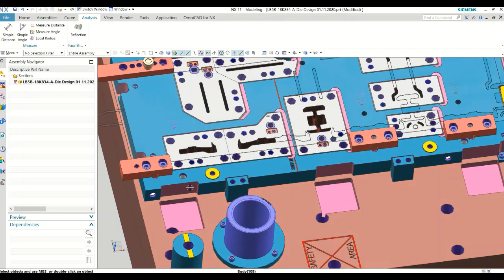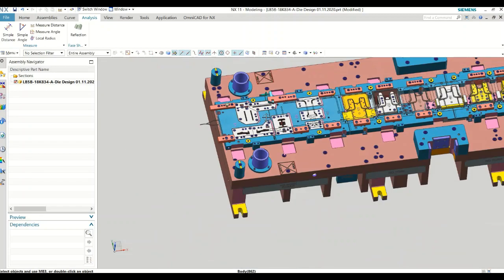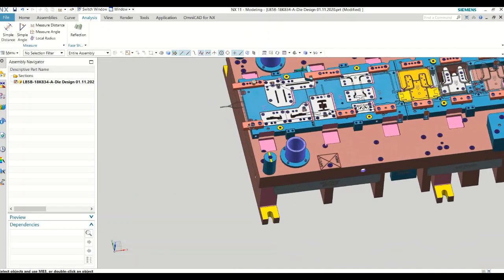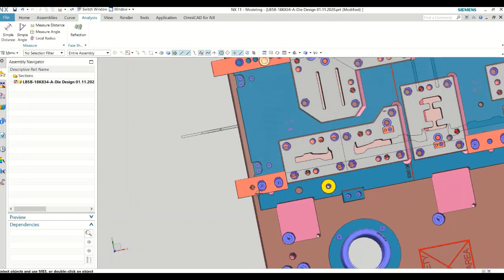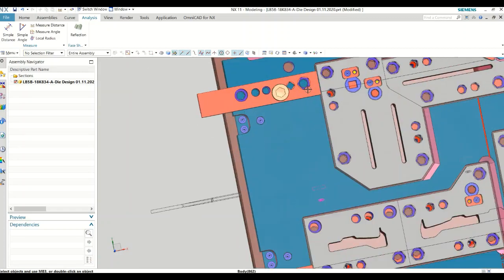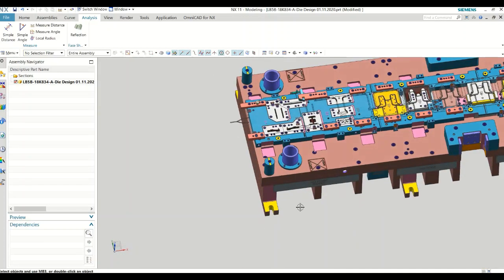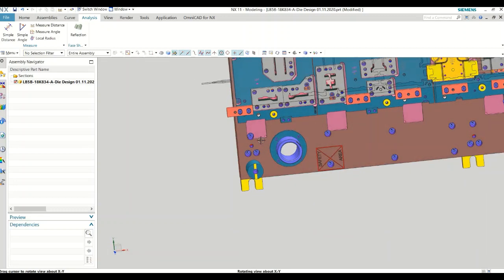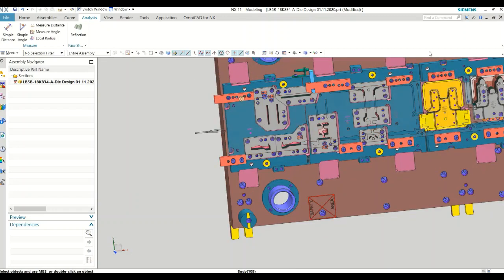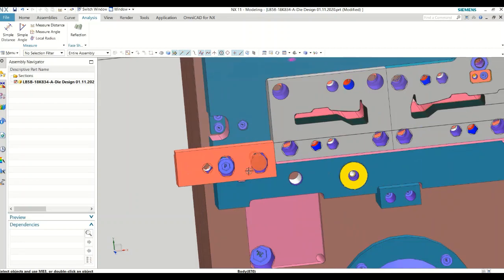Now these are stock guides. Here is a stock guide, here is a stock guide. You see these two are movable and this one is fixed. This is the front side. Because our stock, the coil width, could be less or more. It has a tolerance, so within that range it might be less or more. So you need to adjust it. Every time during setting, you might need to move it in or move it back.